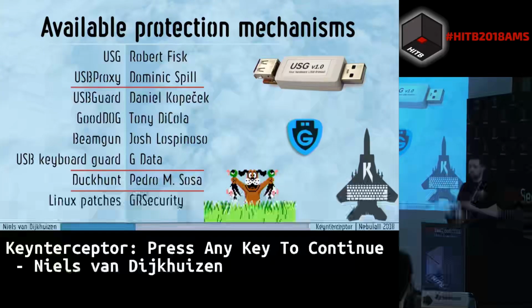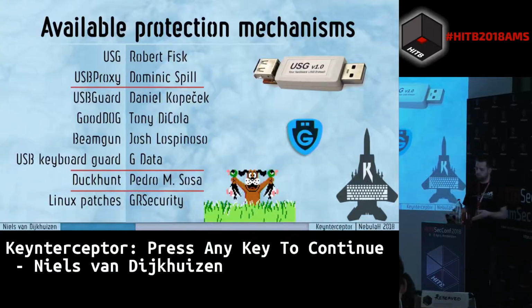Essentially, this device sees re-enumeration. That's the process where normally if you plug in a USB device in a host, we do USB enumeration to see which devices are there, and if it presents itself while connected as a different device, that gets blocked. So in order to bypass this, we have to have the functionality within the device without reconfiguring.